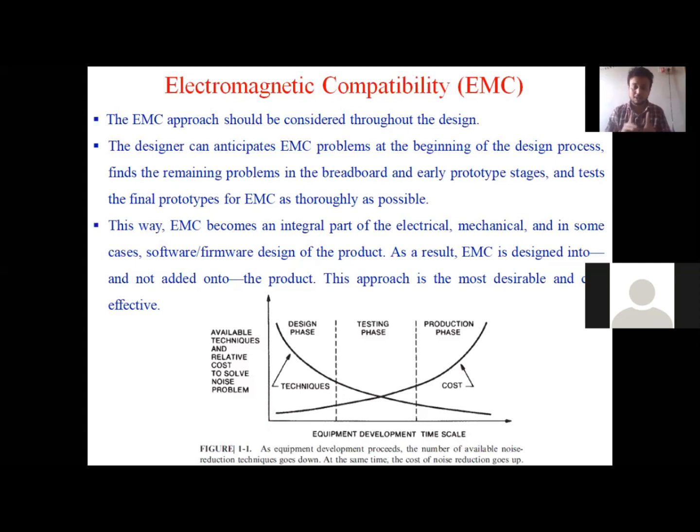So you should initially, while designing itself, separate the two conductors by sufficient distances so that the magnetic coupling that is happening between the two conductors can be reduced to a great level, so that the device is made compatible to electromagnetic environment. It's here itself.